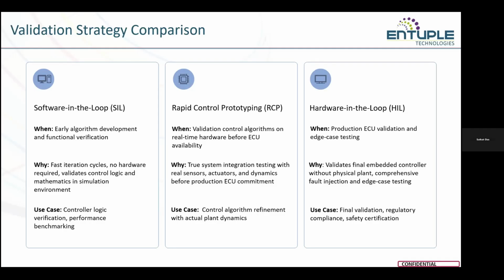Finally, we'll move on to hardware in loop, or HIL system. HIL is typically used before production, where the actual embedded controller is tested against a real-time simulated plant. Why a real-time simulated plant? Because HIL allows safe testing.